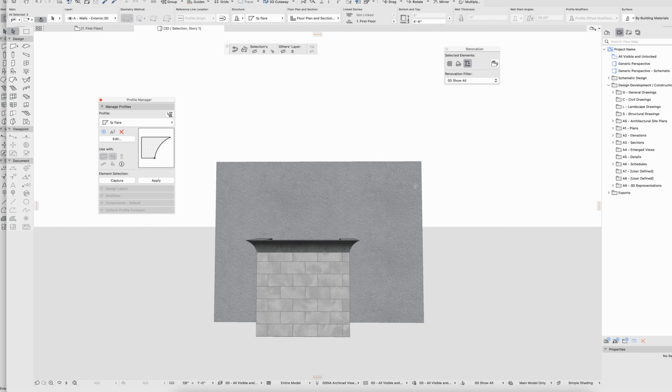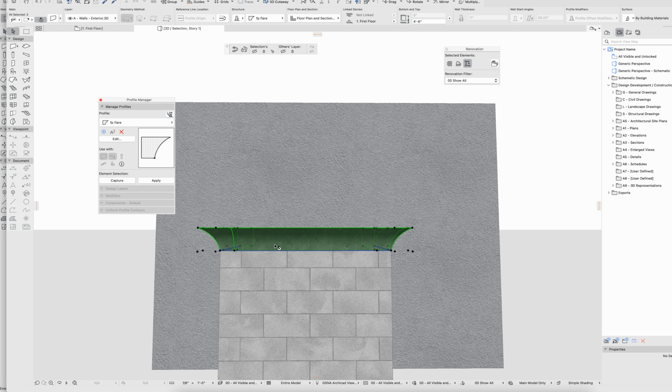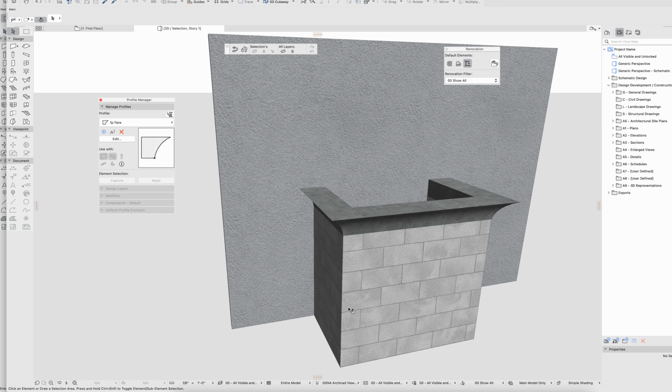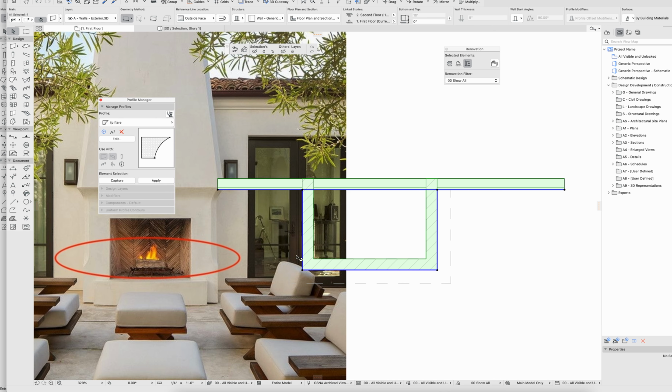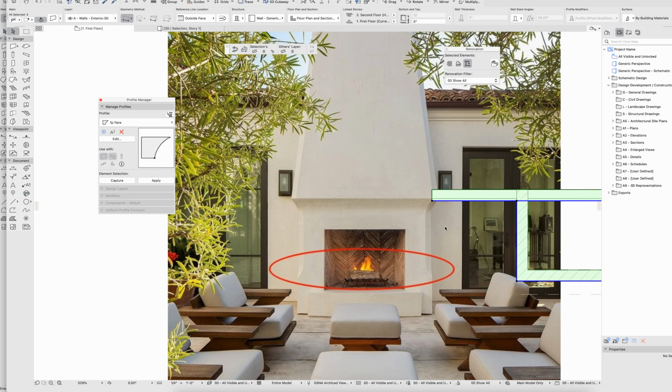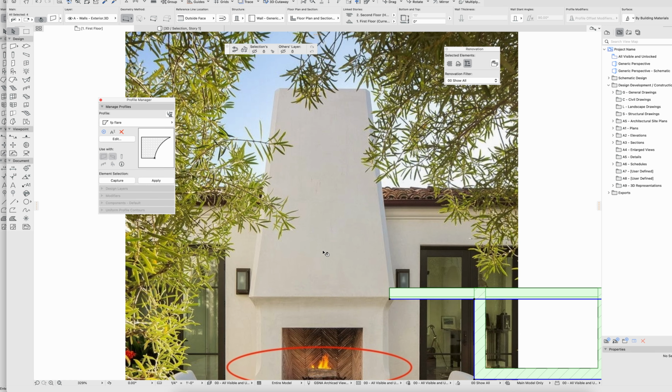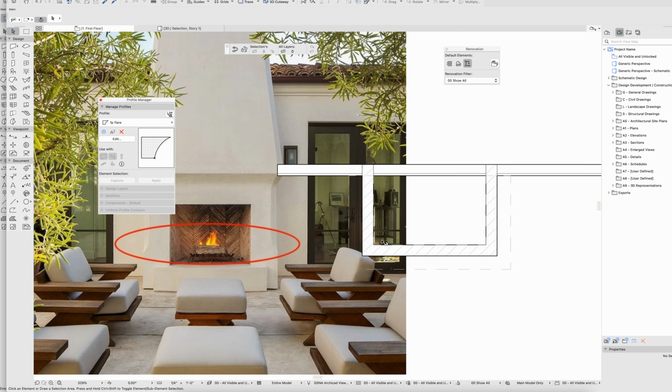We'll apply that profile. That's looking okay. We just have to get that chamfer in there now. I'll figure out how to route that back. So there's that piece, and then we need a piece that goes up from there. It looks like this plane right here is vertical, and then the sides chamfer in. So what are the sides going in at? What is that angle? Looks like maybe about an 80-degree angle.